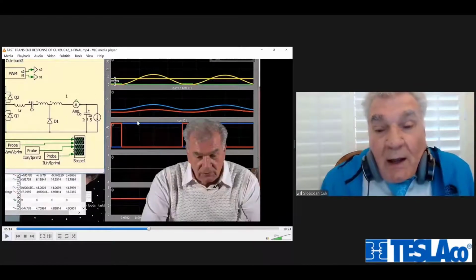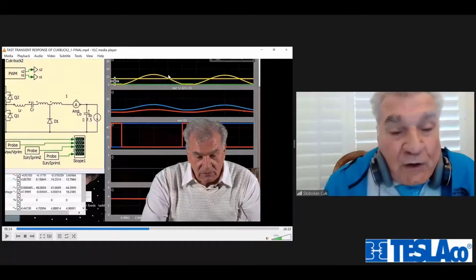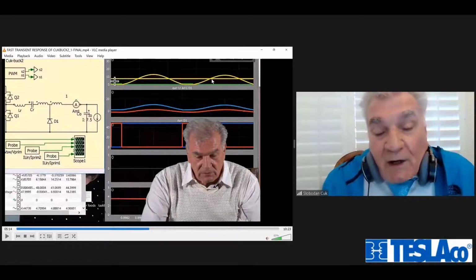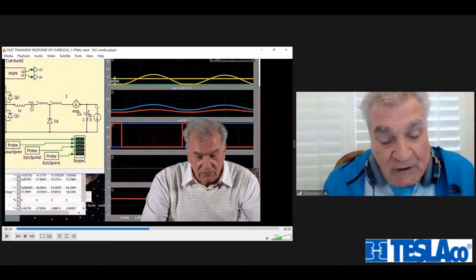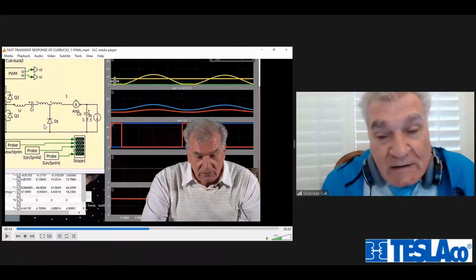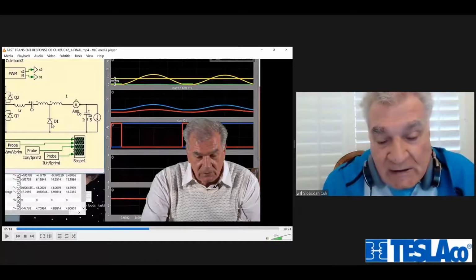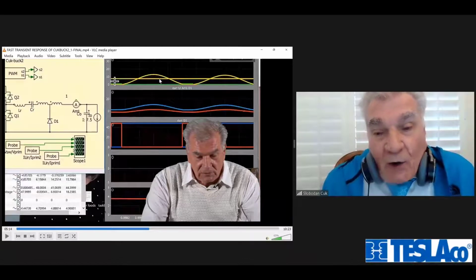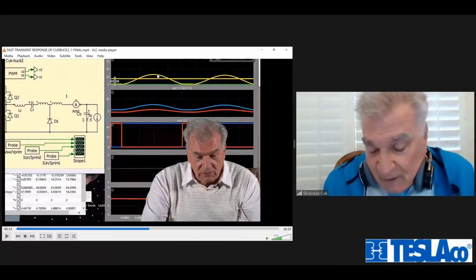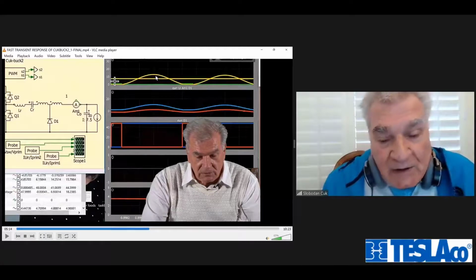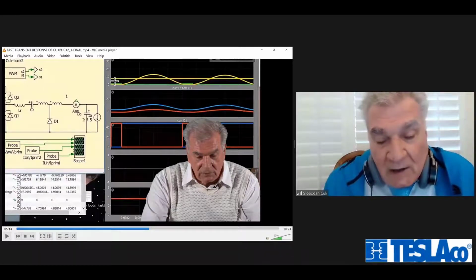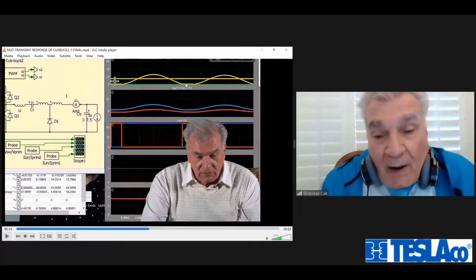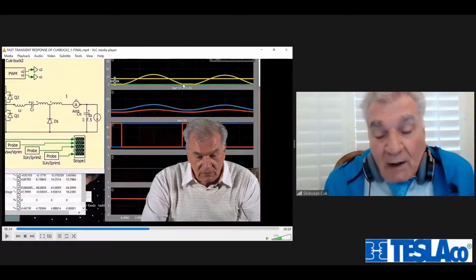You see my point? The converter is not a voltage to voltage converter. It is a voltage to current converter, where the output current of 15 amps dictates the peak to peak current drawn from the diode. This is what you need to have a fast transient for a microprocessor drive on 1 volt going from 100 amps down to 20 amps. It never changes mode of operation. It can operate with no feedback. It operates at 99.5% efficiency, and it has everything in a single converter, operating at 100 kilohertz, with a fast transient. It doesn't need 12 buck converters and 12 magnetics. It has only one magnetic, okay?